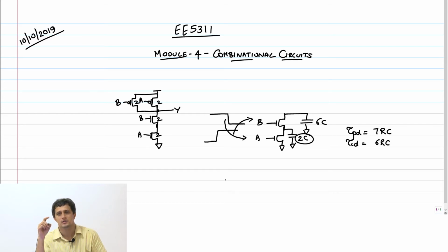The top transistor would have switched to logic 1. It would have sort of charged this intermediate capacitance also to VDD minus VT, and it will be waiting. When the new input comes and switches, then it still has to discharge both capacitors. Therefore, the signal which arrives last, that is the timing critical signal.